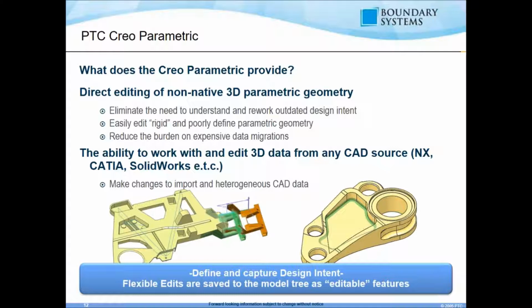Without having to import or convert or get a STEP file or an IGES file or Parasolid or any of that, right? And then not only do you have that ability, you can also then start to use Creo's flexible modeling capability in cases where you do want to make some design changes to start to intelligently select different faces, move different items, change radii, move different features one way or the other, and start to make some design changes to whatever model you need to make the design changes to.